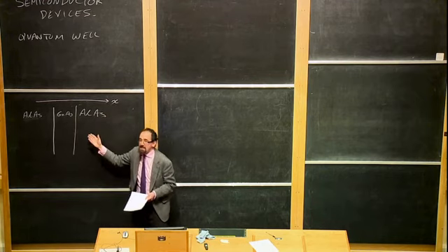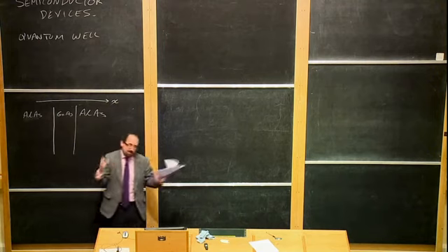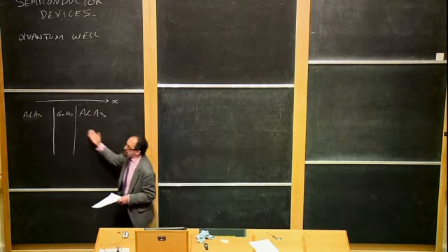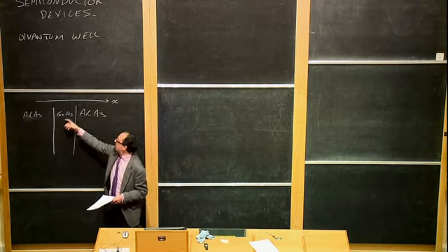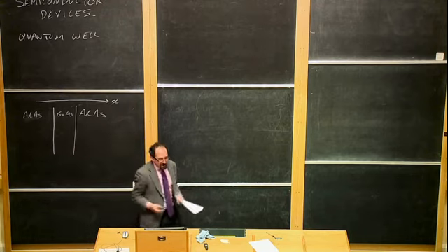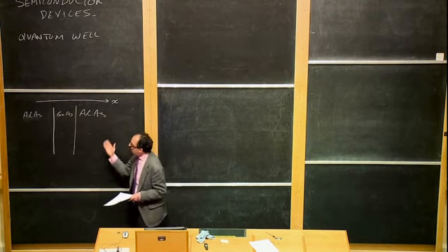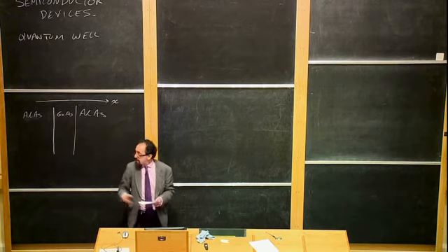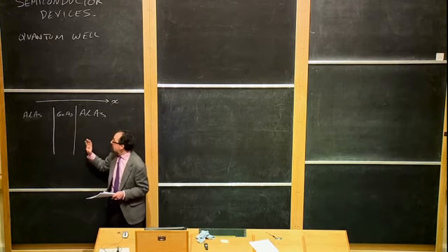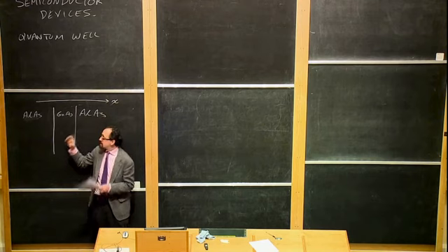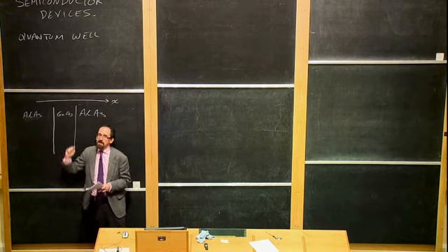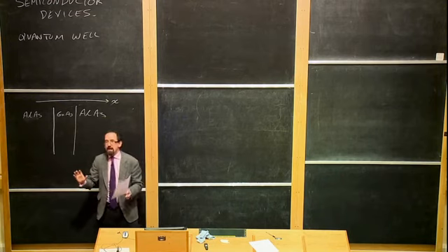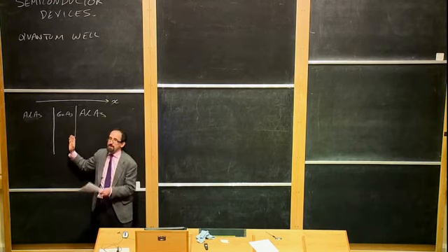And we've actually studied this material before, gallium arsenide. And remember, it has a zinc blende structure. It's FCC with a basis. Aluminum arsenide is just like gallium arsenide, except you replace the gallium with aluminum, so it's also FCC with a basis. And the reason that I've chosen these materials, aluminum arsenide and gallium arsenide, is that there's a little bit of a gift of nature here. It turns out that the lattice constant, the size of the unit cell, for gallium arsenide and aluminum arsenide is extremely, extremely precisely the same. It's just something that randomly occurs, which makes these very desirable materials to work with.